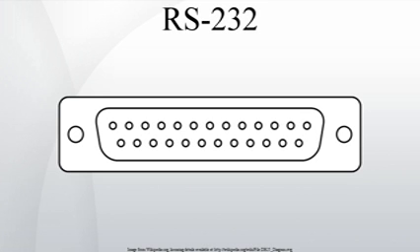Some simply display the signals as waveforms. More elaborate versions include the ability to decode characters in ASCII or other common codes and to interpret common protocols used over RS-232 such as SDLC, HDLC, DDCMP, and X.25. Serial line analyzers are available as standalone units, as software and interface cables for general-purpose logic analyzers and oscilloscopes, and as programs that run on common personal computers.